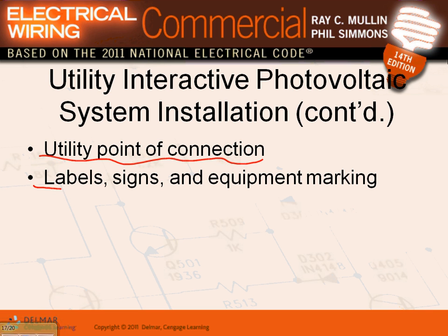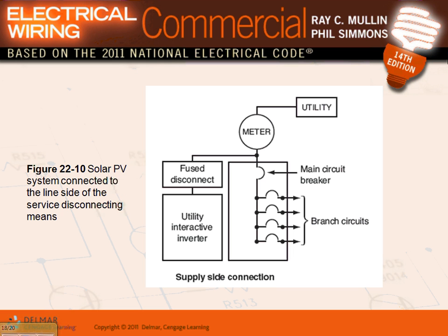When you connect with the utility, you have to put a label and a sign and mark the equipment that this is a source of power coming from the solar system. There's some signs and equipment marking that you have to do. Okay, connecting with the utility.